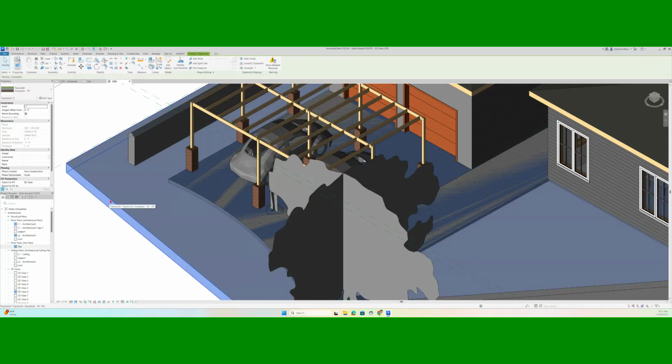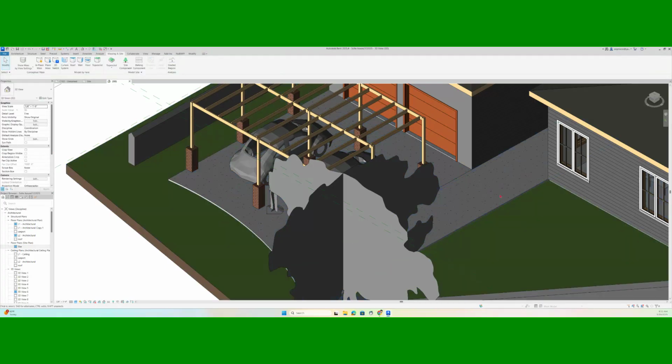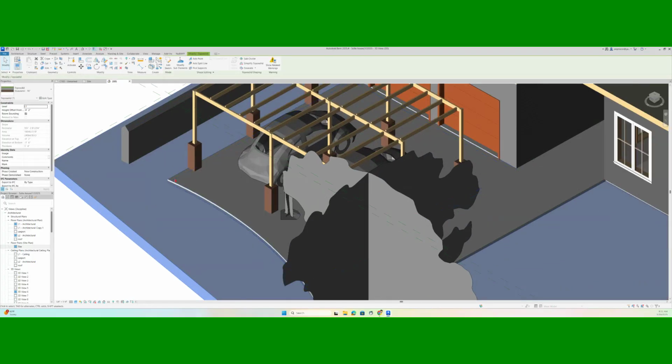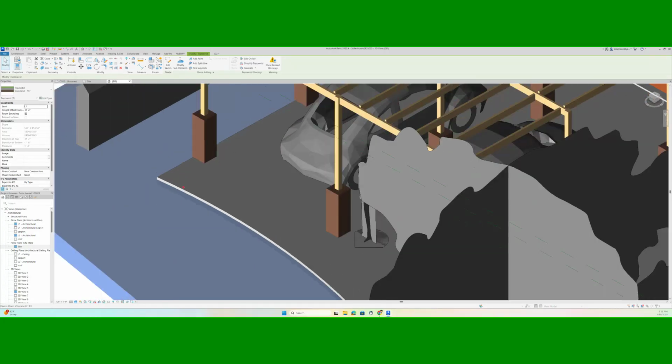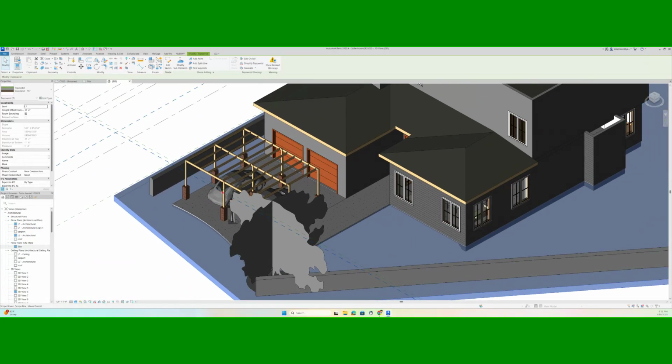So best if you graph your topo soil, select the topo soil, and on the height offset from, you can go here for a minus 0 space 1 inch or 0 space 2 inches and apply it. And that's what it's telling us. Actually, yes, there's an overlap between sidewalk floors foundation with the topo soil, but not anything to worry about.